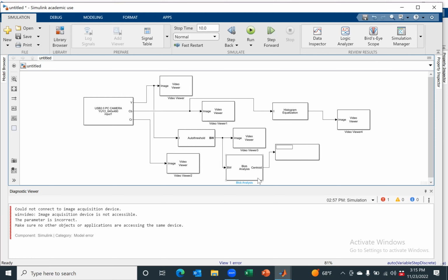So you have a scale factor, which means one X pixel is equal to maybe 2 millimeters. One Y pixel maybe is equal to 5 millimeters. So you can convert that pixelated image into the world coordinate frame or world dimension. That's exactly what you need to do when you are doing the image processing.